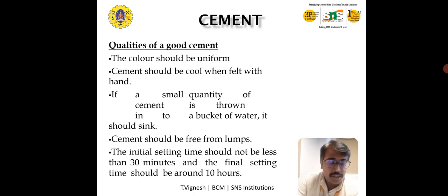The initial setting time should not be less than 30 minutes, and the final setting time should be around 10 hours. If the proper setting time is not given, cracks can form in the wall, and once cracks are formed the wall loses its strength.